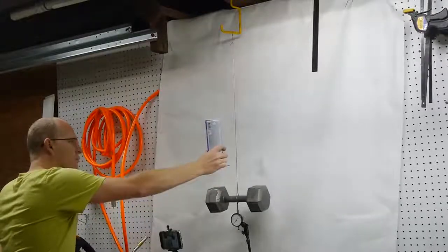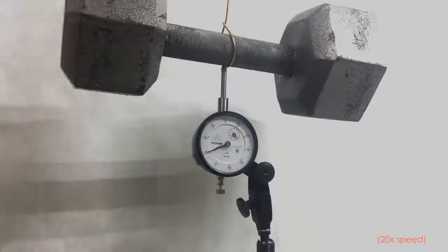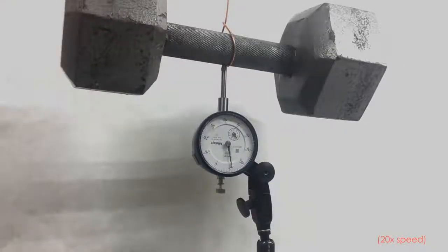Thermal movement can generate tremendous amounts of internal stress. Watch how this wire can lift up a weight just by heating it up and cooling it down. So the other way to accommodate thermal movement is just to allow your design the freedom to move as it so desires. But sometimes it's easier said than done, especially for large civil structures.